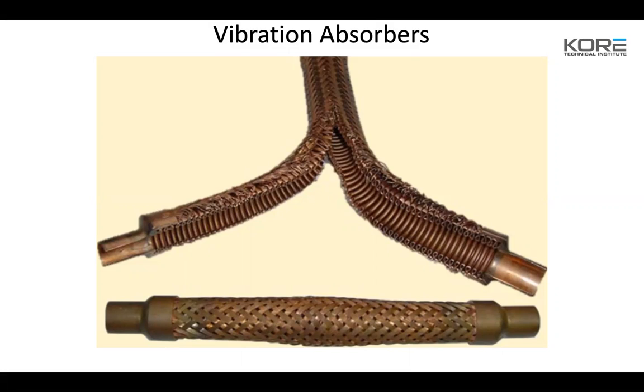So everything's rigid mount now, in rigid pipe. So that's the importance when you guys are dealing with parallels and stuff. Make sure you're checking your rotations on your compressors. They should all be the same. We found a lot of big rack leaks on discharge lines where 2 or 3 of the compressors had been wired backwards and were running opposite on rotations, which causes an insane amount of harmonics on the rack.